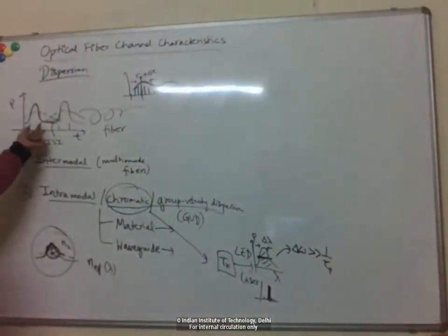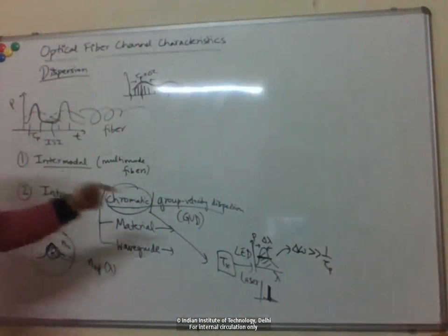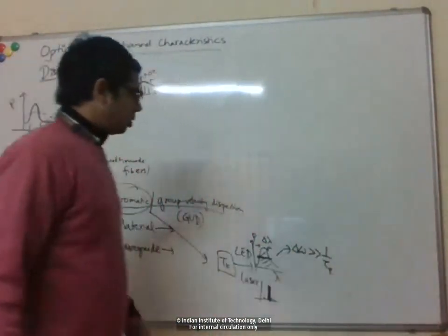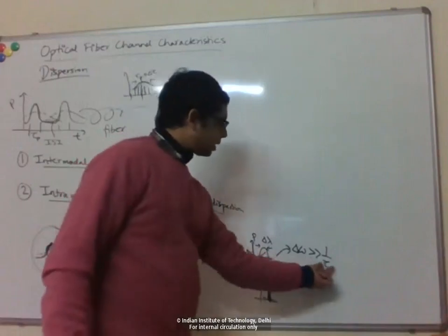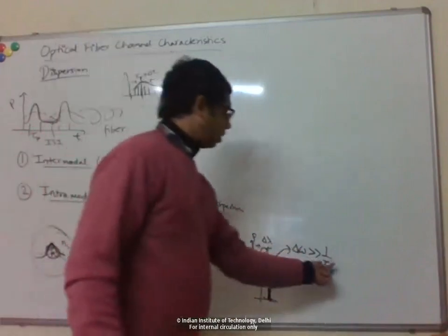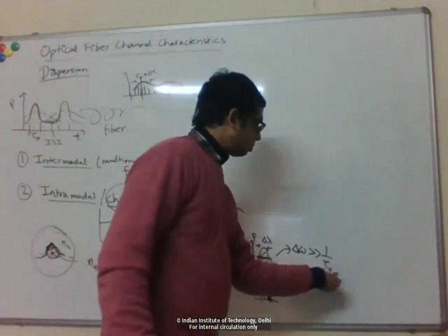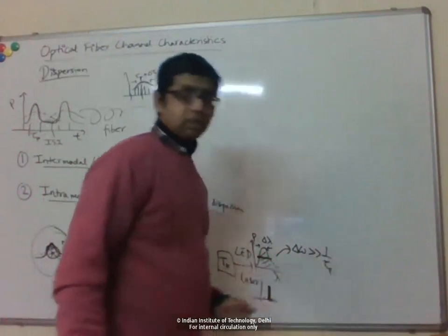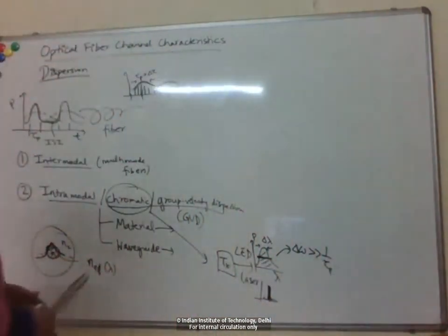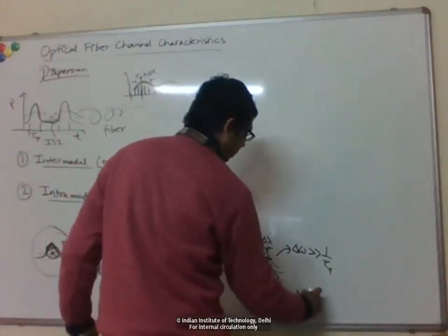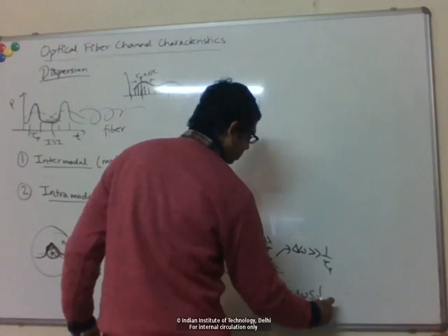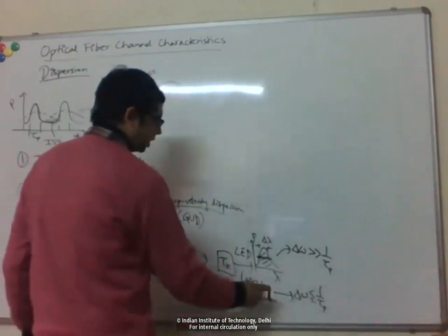So there's a bandwidth defined just by the pulse rate here, which you can again roughly imagine as the data rate, 1 over tau p. So for incoherent sources like LEDs, the spectral width of the source would be much bigger than the data rate or the inverse pulse width. Whereas for lasers, we are in the opposite regime, right? So it's almost like a single frequency.